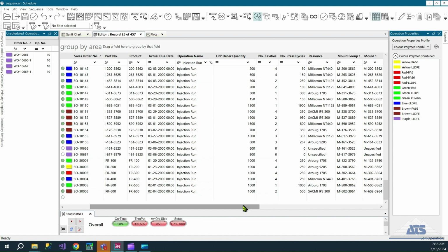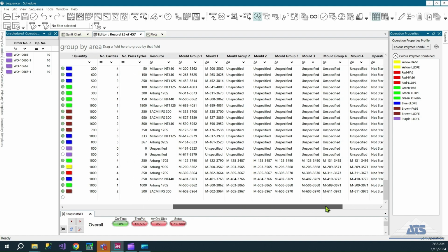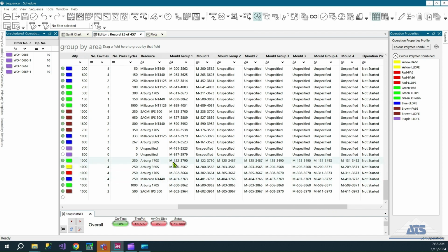I know down here at the bottom of my screen, we have multiple molds. In this case, I set this one up just to show 4 different molds within a frame producing different quantities based upon the individual number of cavities per mold. So it can get a little complex with the numbers that you calculate, but it's very easy to insert the correct equation to verify the number of cavities I have, what my demand number is, and then that generates the number of press cycles to kick out the molds when they're finished.